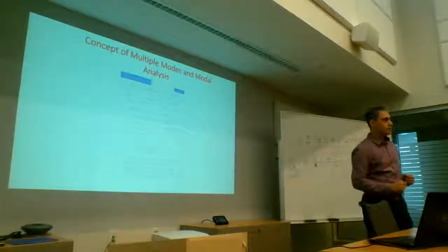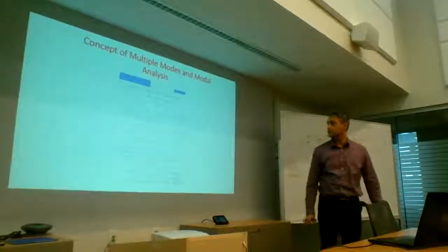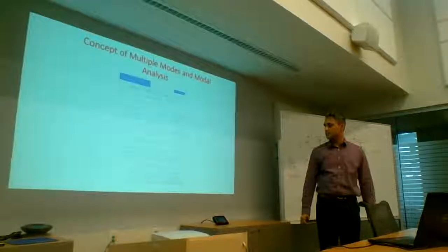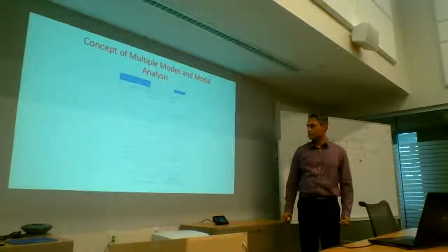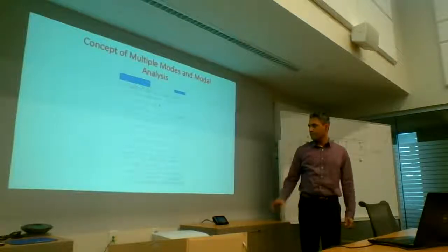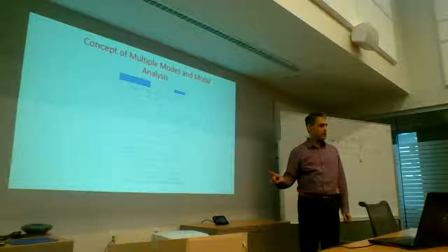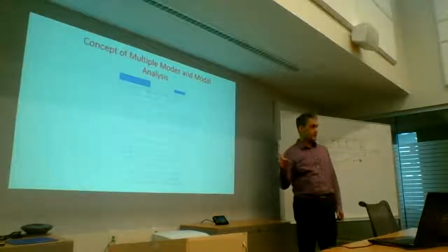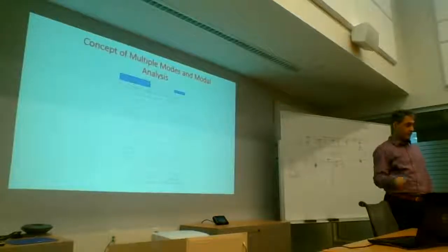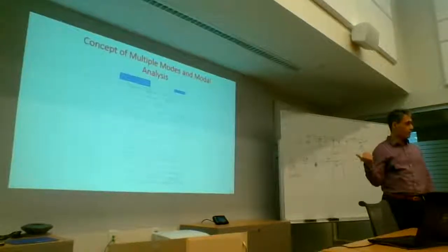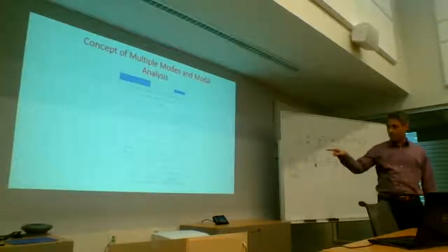Yes, sir. You said this equation number F1? Yeah, this one. This A is a diagonal matrix, okay. But C and K, they are all diagonal matrices. I should have mentioned that. This is true for classical damping. C becomes a diagonal matrix. When it's not classical, then you cannot use the classical response spectrum analysis. Okay, and the same thing with the K.